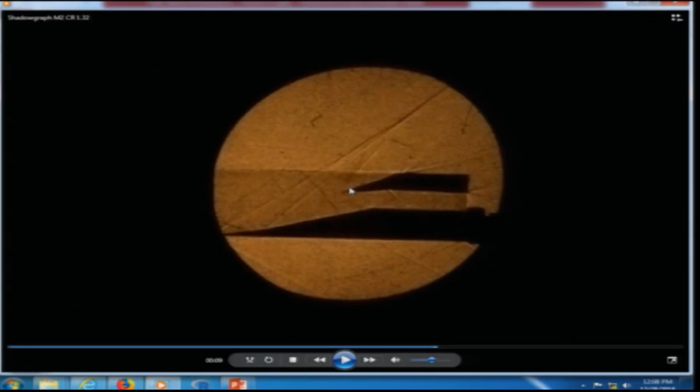At this point, when the flow is entering fully, at the tip there is also an attached oblique shock, because it finds a conical tip, a sharp nose here, and hence theta is less than theta maximum, so an oblique shock of something like this is obtained.